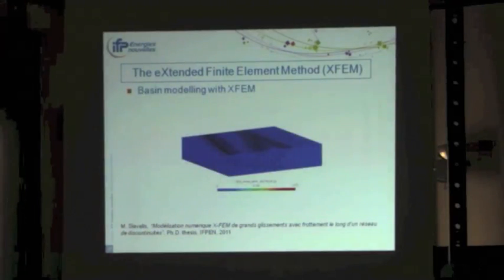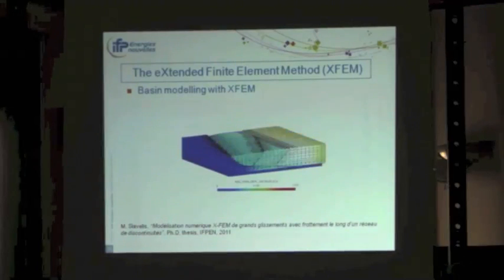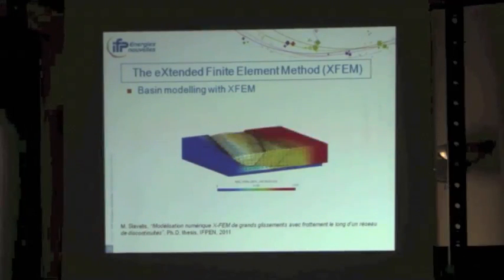So this is an example of a basin modeling with the XFEM. We've got the large sliding between blocks. This is the work of a former PhD student, Maximilien Schiavelis. And the initial mesh is only constituted of hexahedrons.